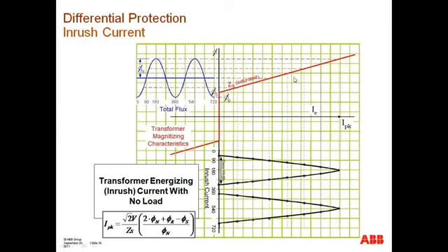When plotted on the BH curve of the transformer, we end up with these inrush current pulses, which can have very high area on the positive plane, or very high area on the negative plane, but not much contribution on the other, depending on how the flux waveform is shifted. In the case of positive remanence, you end up with a positive current waveform. In the case of negative remanence, your total flux waveform is shifted down, and you end up with pretty much all negative current pulses. And these current pulses, given their width, are consistent with the footprint of second harmonics.